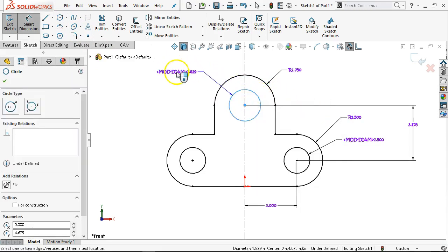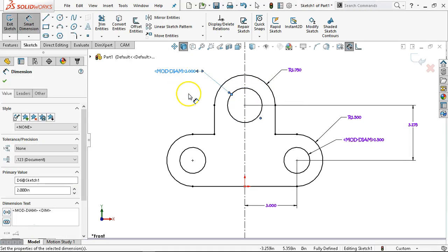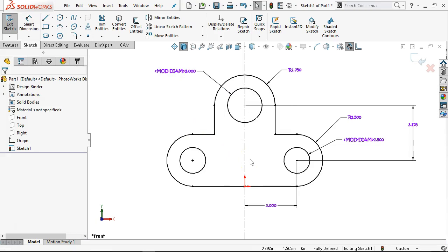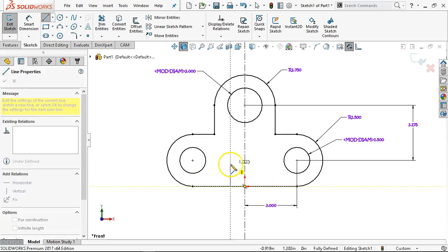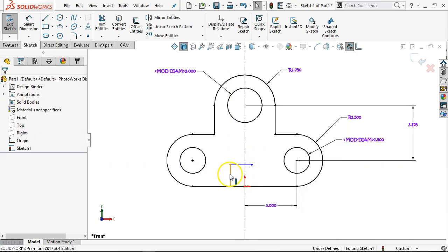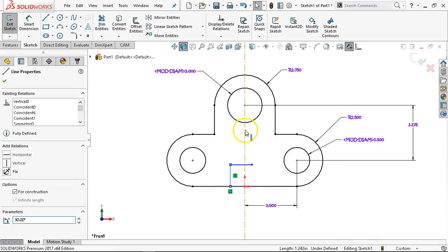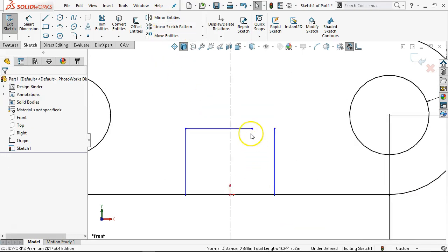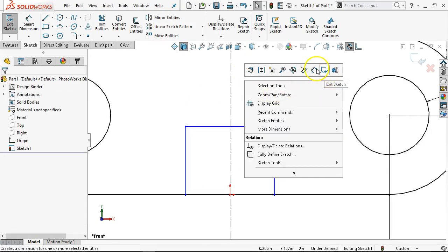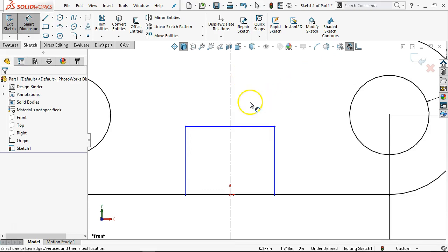All right, we'll put our 2-inch diameter in. And at this point, this is a standard extrusion. There's one region, this will extrude out, and I could go ahead and put the hole in the box in separately. What I'm seeing more often is that we're drawing in the geometry, so I'll go ahead and put that in. The other mirror is to select, control, select, since I only have one object, and then connect those dots. So that was 2 inches by 1.5.